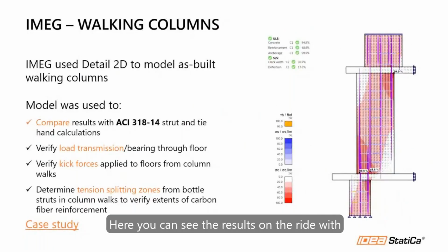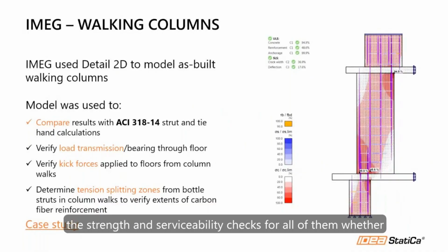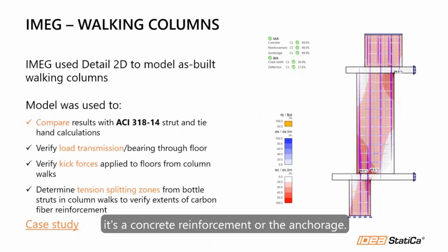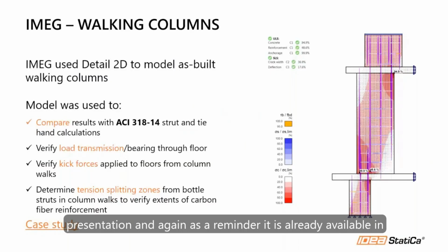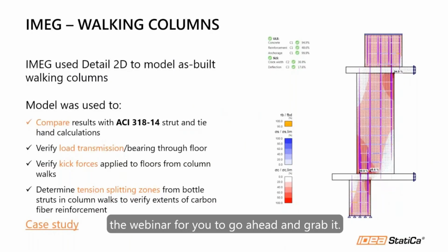Here you can see the results on the right with the strength and serviceability checks for all of them, whether it's the concrete, the reinforcement, or the anchorage. You can also see the stress fields clearly visualized from the column to floor transition. And in case you're interested in reading the full article about it, it will be linked in the PowerPoint presentation. And again, as a reminder, it is already available in the webinar for you to go ahead and grab it.